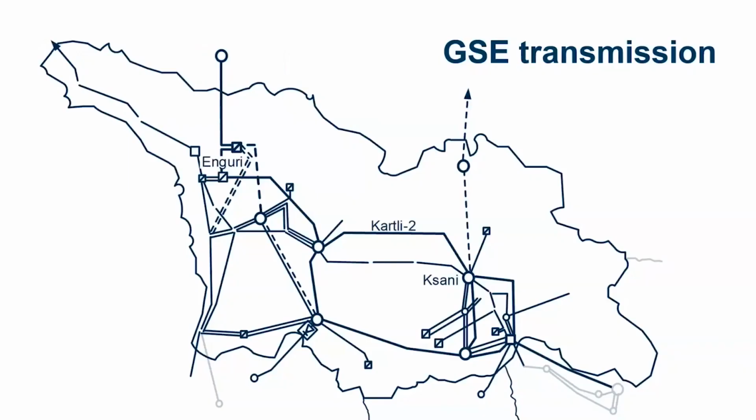Georgia State Electric System has implemented a centralized and distributed remedial action scheme to maintain power system stability in the Republic of Georgia. The countrywide remedial action scheme was based on customized operating principles devised especially for GSE's power system. The system started out as a simple 2 substation system and grew to now more than 30 distributed controllers. The figure here shows a high-level picture of GSE's power system.